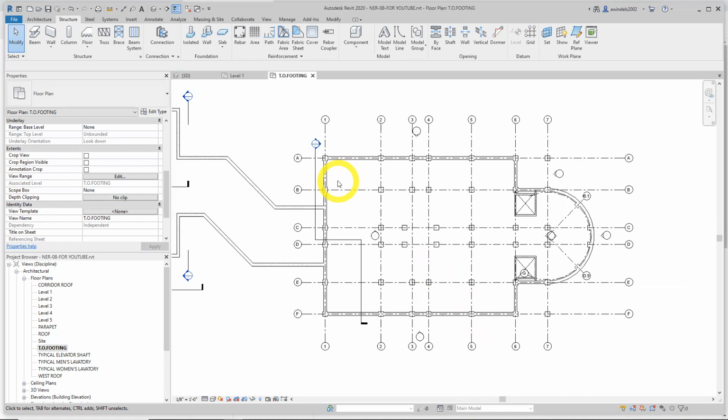And that's the end of the chapter. You're better at structural grids, the backbone of any good structural engineer or design, adding columns and grid lines, columns to those grid lines, at different offsets, adding structural beams to a model with some braces. You added a couple of those and some beam systems in between, a complete polygon, so to speak, of beams in between them.